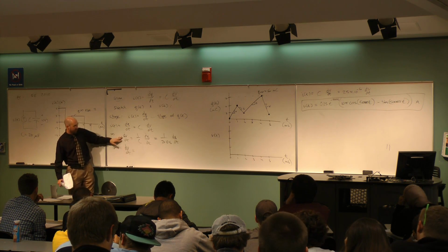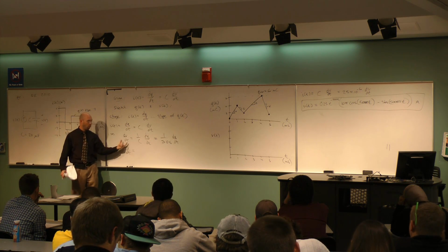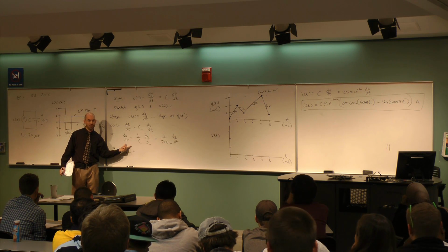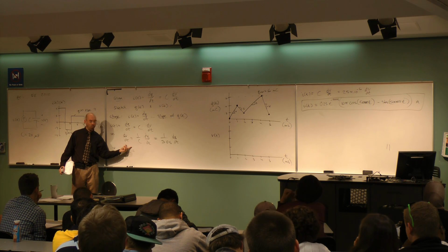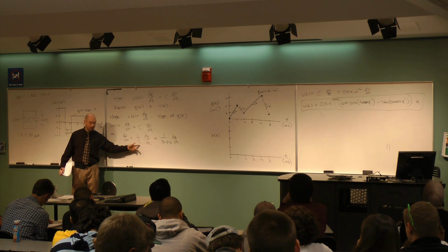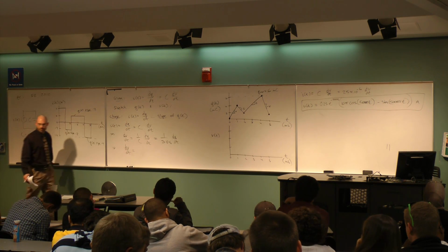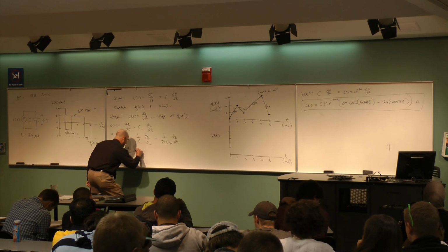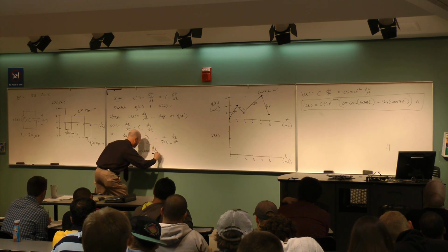So what I'm doing here is solving for dv dt because I'm trying to plot v, and I want to know what is the slope of this graph. I already know it's going to be lines. I just need to know the slope in each interval. You guys with me? So we solve for that. That puts a 1 over C here. So I got 1 over 20 e minus 6, which is how much? 50,000. Okay? So I got 50,000 times the dq dt.